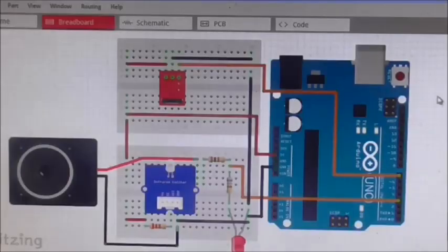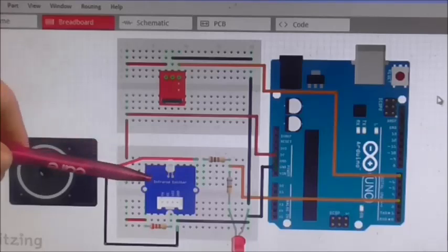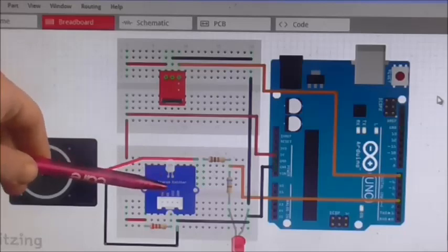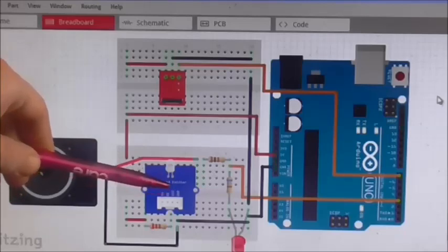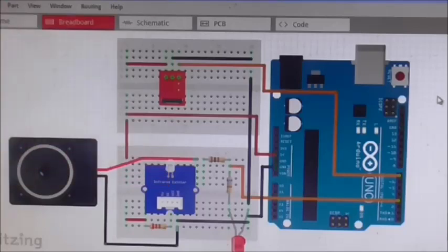There's a little wiring diagram of what I intend to do here, and as you can see I'm using a microcontroller. Don't really need to, but it makes it much easier than using discrete components for the rest of the circuit. For our purposes, what we're interested in is these two things here. So we have an infrared emitter, and basically that is an LED, and it's been put onto a breakout board to make it more breadboard friendly. The infrared LED takes 1.2 volts forward and is made of gallium and arsenic.